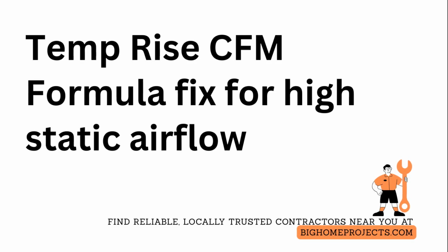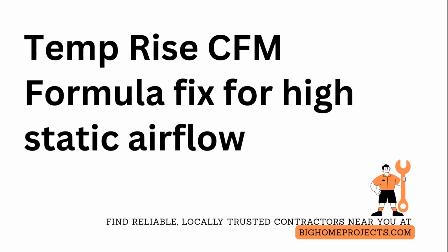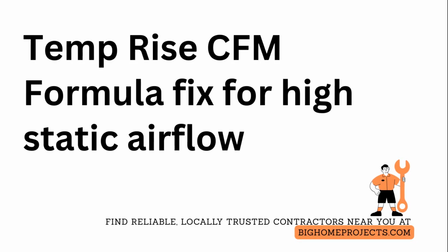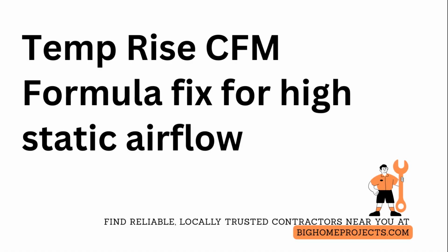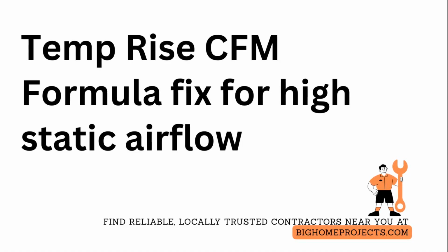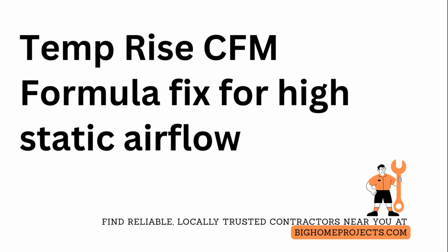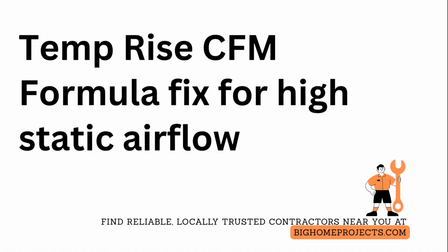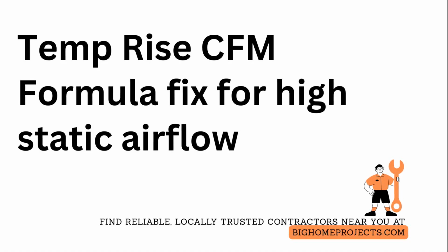Measure airflow cubic feet per minute with the heating, ventilation, and air conditioning temperature rise formula by multiplying furnace output in British thermal units by 0.008 and dividing by the measured supply minus return temperature rise. Then use that number to flag low airflow or high airflow conditions that hurt efficiency, comfort, and equipment life.